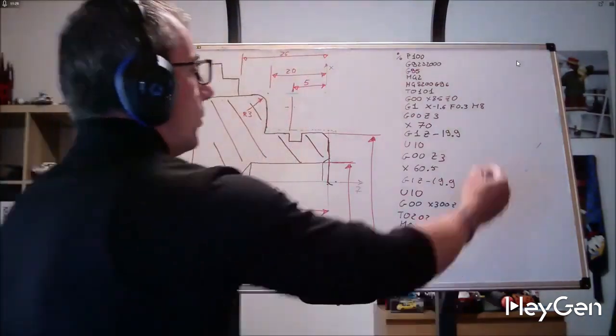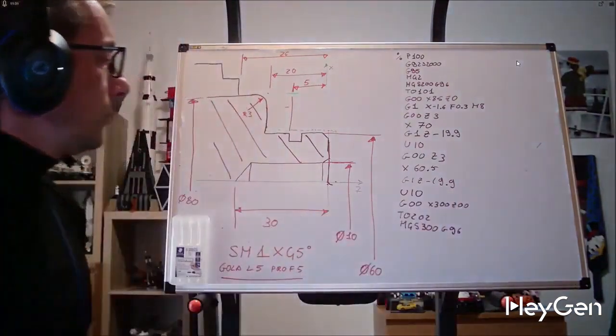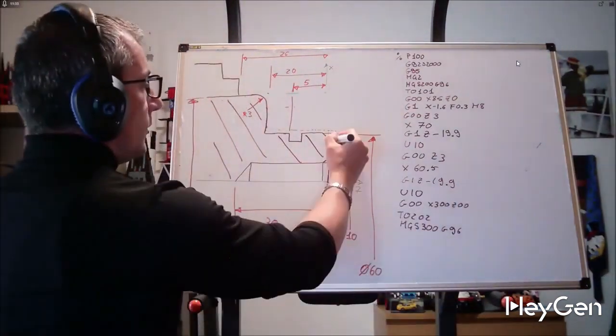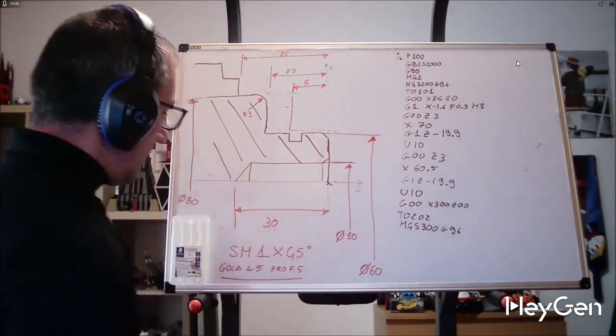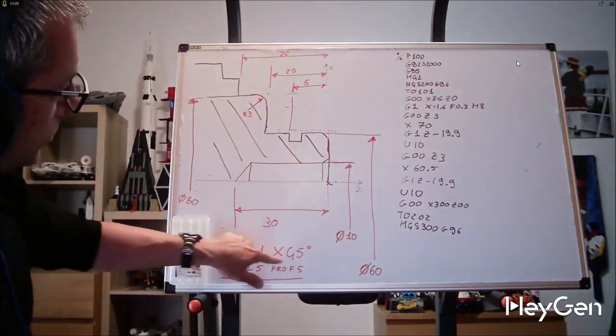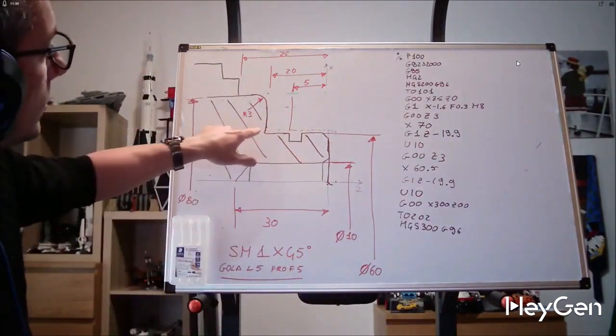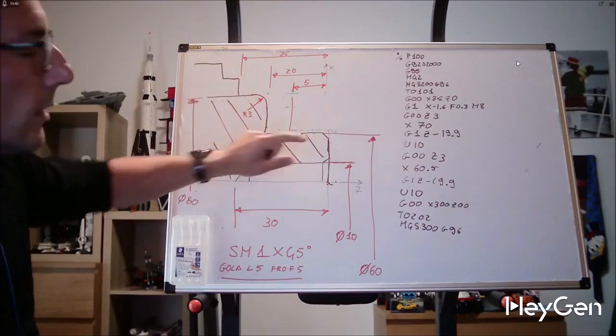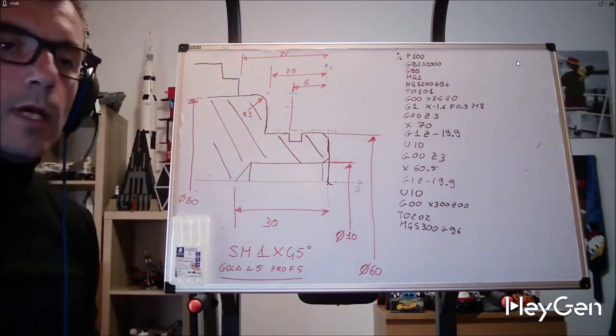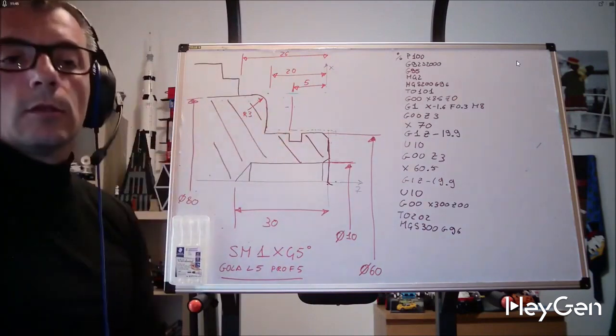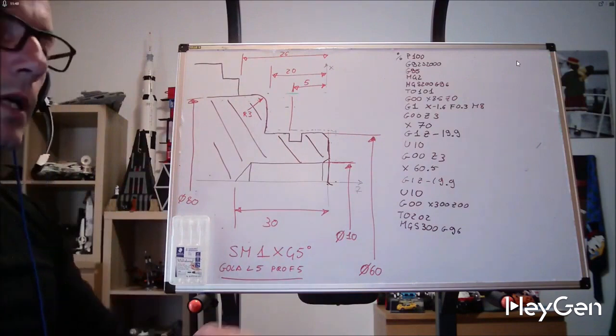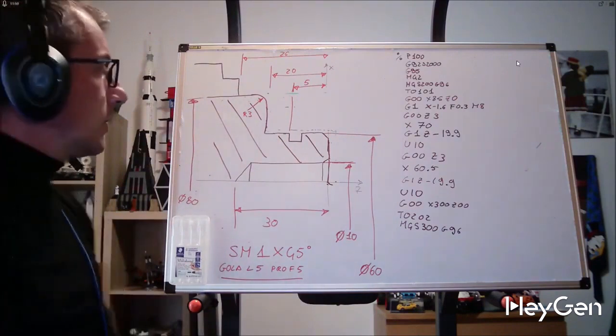Here I move over and do the finishing. I will position myself. So we have chamfers of 45, a cylindrical turning, a radius, and a groove that we will ignore for now, because to finish we will use a DNMG insert, a VNMG, at 35 degrees and 55 degrees.